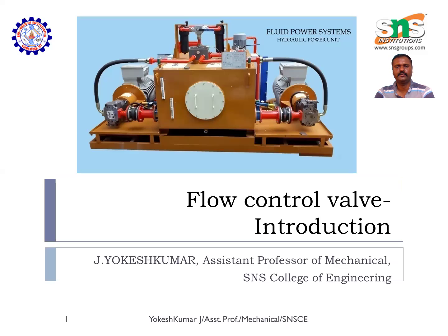In the previous video, we have discussed about the flow control. Why flow control is necessary, why we have to control the velocity or the speed of the actuator. Since the flow is directly related with the speed or the velocity of the actuator, by controlling the flow rate, we can control the velocity of the actuator.